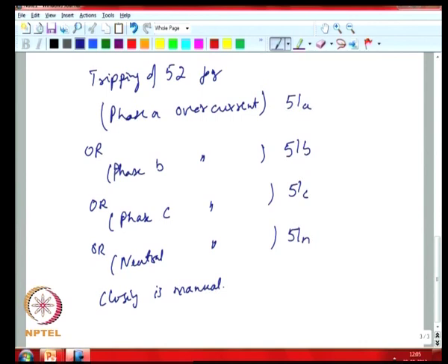Okay. If you look at the actual computation of whether there is an overcurrent happening or some action that needs to be taken, in typical power protection applications, you are looking at sampling rates of 8 to 16 times your normal 50 hertz rate.